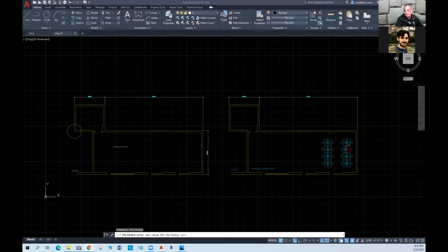And so when we set it to 1, as it is currently the default, PSLT scale set to 1, that's the default. What it means is that whatever scale factor I have as a global LT scale, the one that we just did, will be multiplied by the scale of the viewport. And that multiplication is what's going to define the visibility of the line types in that particular viewport. And so it could become really complex to do that.